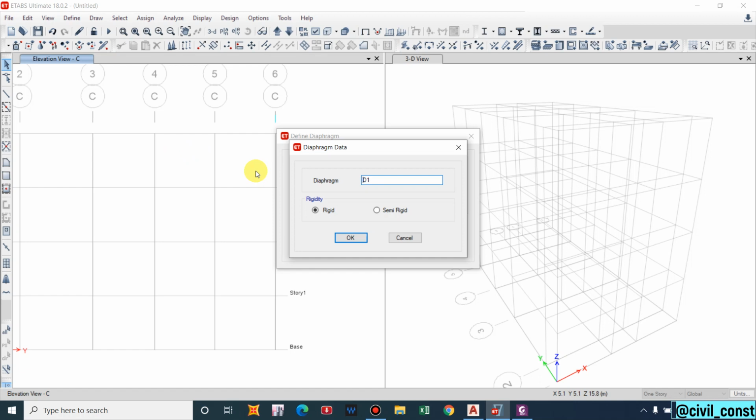And the semi-rigid should be modeled when significant in-plane deformation occurs, taking into account the respective stiffness of the diaphragm. So basically, a semi-rigid option will be selected when a more detailed analysis is to be done, when the number of modes is higher in the building considering the eccentricity in the building. So that may be the option for the semi-rigid.